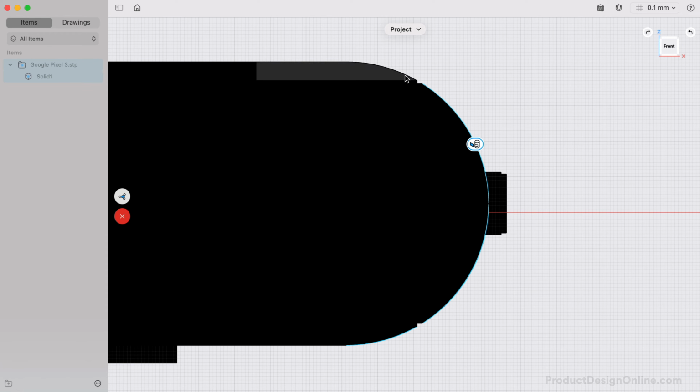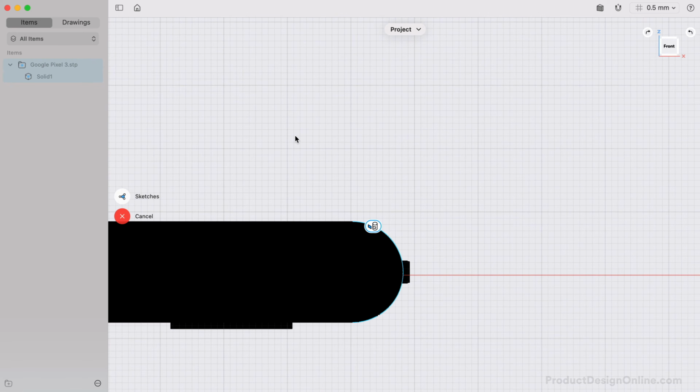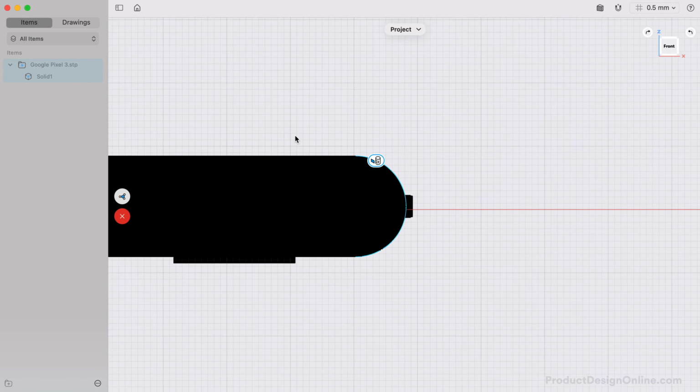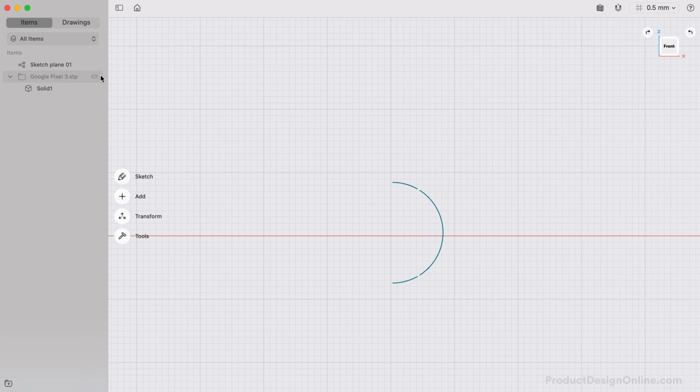With my file, I'll need to do this a total of 5 times as the existing faces of the 3D body break up the sketches. We also need to double check the tool is set to the Sketches option. This ensures we create a new sketch instead of imprinting the edges on our existing body. You can toggle this anytime before completing the tool. Select the planar face to project the sketches onto, then select the blue check mark when done. I'll also hide the foam body in the Items Manager so we can see the sketch.